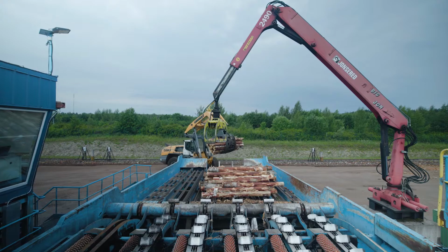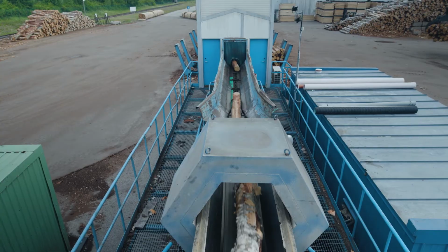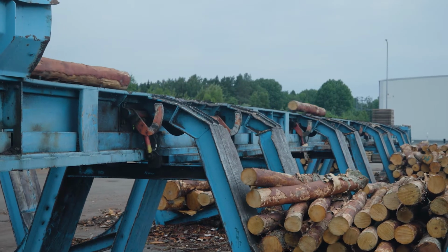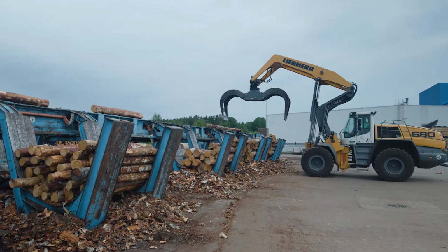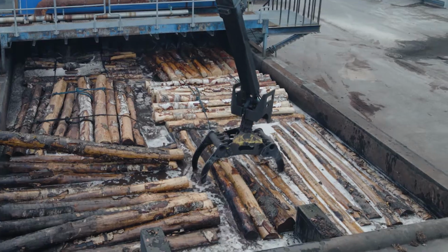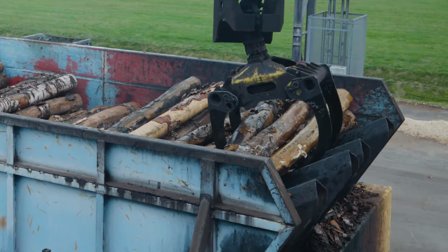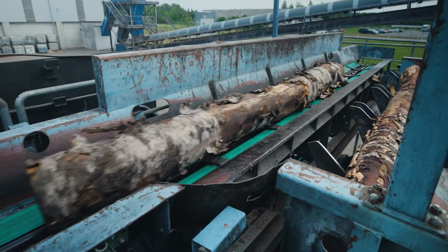The veneer production process starts in the log yard. Logs are sorted into different classes by their length and diameter. Sorting optimizes the soaking, debarking, and cutting stages and minimizes raw material waste. Any waste is usually used for energy or pulp production.